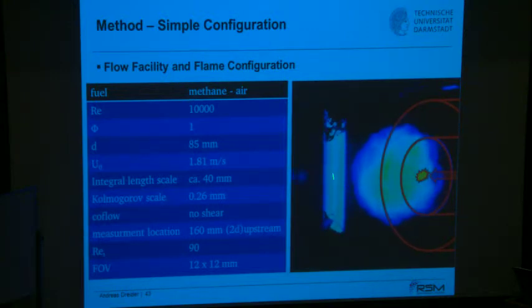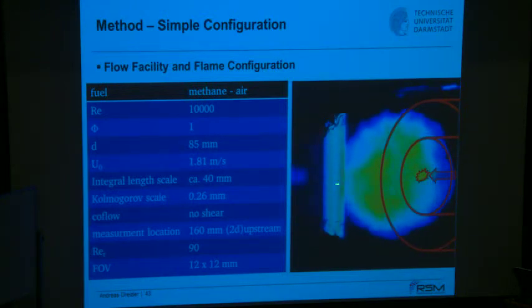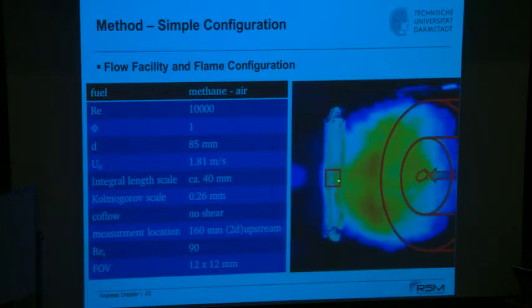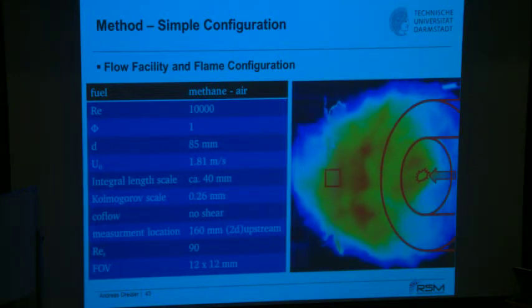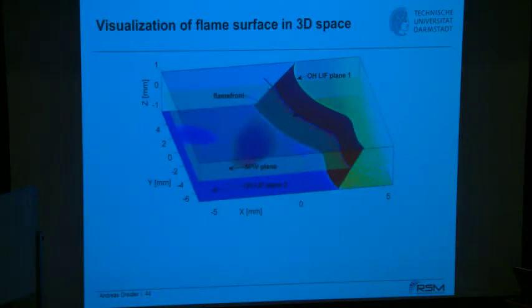This is chemiluminescence. Here you see the Mie scattering, and this red angle says when the data has been taken. Now it was aerosol seeding, as you see here in that case, to demonstrate that. So the particles are vanishing once the flame goes through. So just to show you in slow motion what the experiment actually is doing.